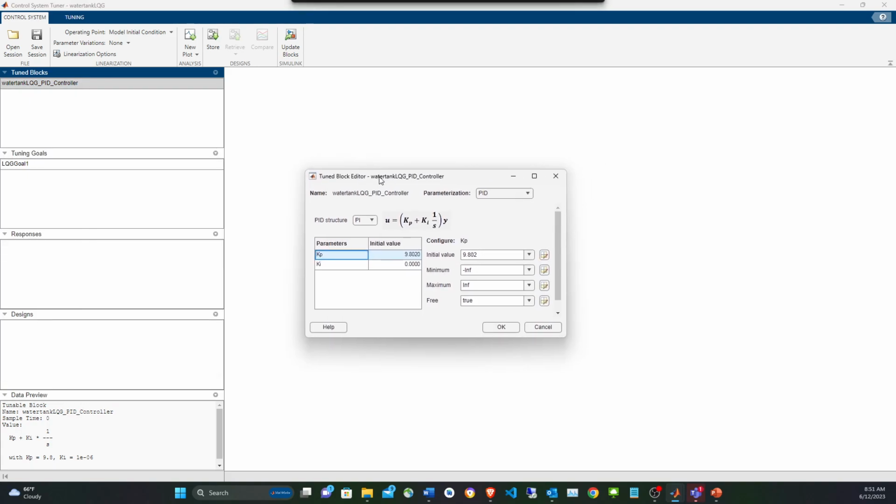And in this case, we are going through a proportional integrative, which falls into a general category of proportional integrative derivative, PID. And you can see the constants for the proportional and the integrative in here. This is actually, yeah, you can see that we have PI, no PID. So that's why you see only those two terms. And the integrative right now is 1e-6.